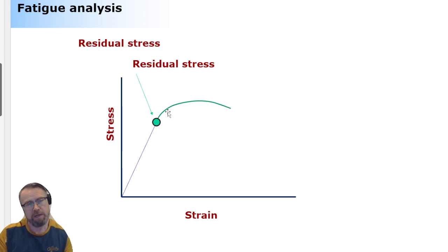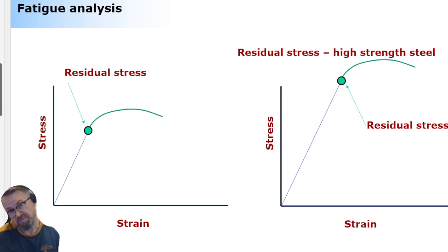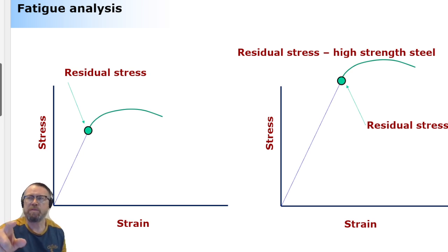The difference between conventional and high strength steel is simply that this linear region is going to be longer in high strength steel. So let's do it. Let's change it. So what's the difference? No difference. Again, the amount of heat we're introducing in the welding process is so significant that regardless of how long your linear region is, you always end up at a point where the linear region turns out to be plastic region. So that's pretty much the help of the high strength steel.